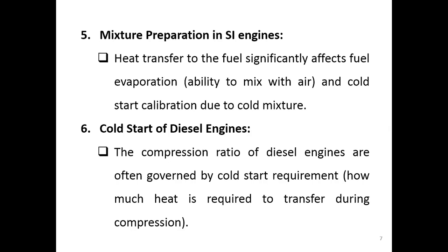So we have to do calibrations that consider this amount of heat transfer when we operate the engine in the winter seasons. And then we have to do another calibration on our engine when we operate the same engine in the hot season, because the direction of heat transfer is changed between the surroundings and our mixtures. Okay, so this will affect the mixture preparation for the SI engine.